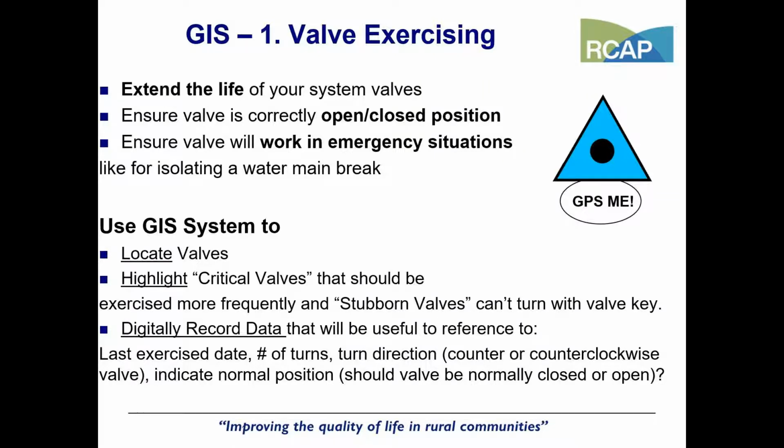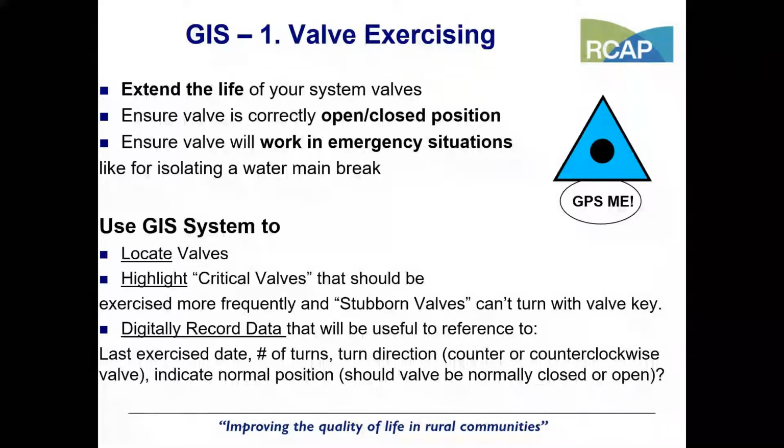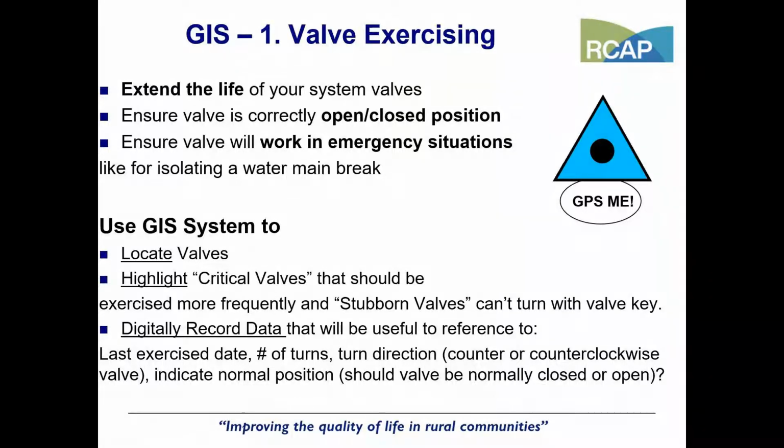Critical valves, knowing where your critical valves are is super important. Highlighting those on the map, we can symbolize that differently, especially if you have a few that you really need to check up on. I know in Kentucky we got a lot of flooding, so having those critical valves mapped out really helped the operators go to those sections to see which parts we have to shut off, and digitally just recording that operation activity.